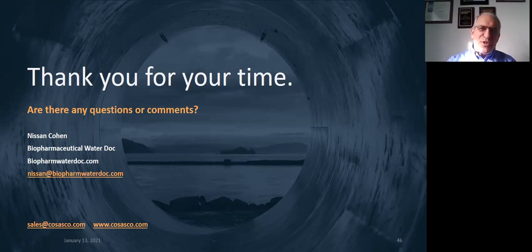So how you establish that is to state unequivocally that Rouge is prevalent in hot water systems. We have hot water systems. We need a mitigation plan. We also want to do the mitigation plan based upon science and technology of having an online Rouge monitor, and not doing it based upon subjective issues of color, discoloration, or QA/QC saying we do everything else once a year, we're going to do this once a year.